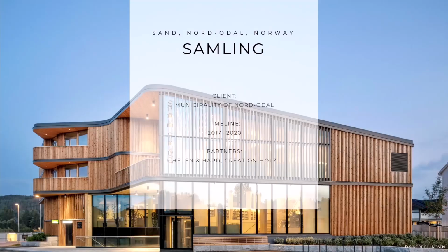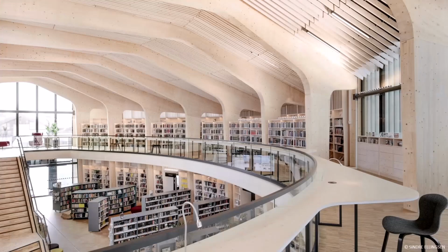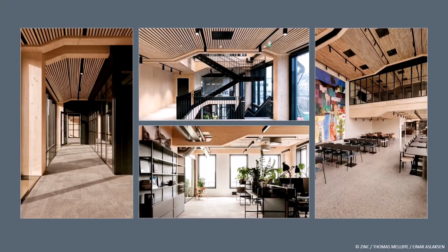Yeah. Another project, again with the same architect, very large portal frames. Timber is not meant to be continuous, so portal frames in timber, it's tough. This is Drammen, a high rise in CLT. Again, possible, but when you have a core, you will never have one core like in concrete that is continuous bottom to top. So you will always have a panelization, no matter how much you push the boundary of production. You will not be able to transport more than 20 meters from Austria to Norway.